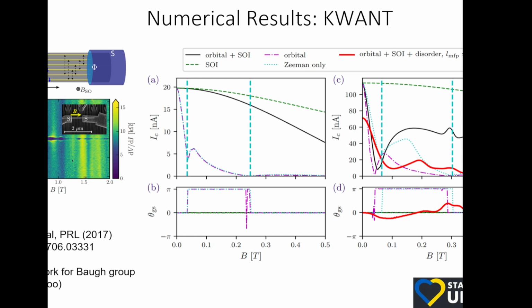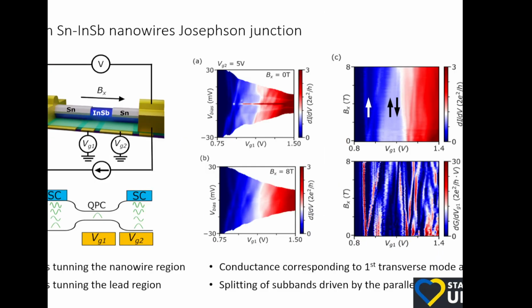Okay, so now I want to talk about the single mode regime. What we are blessed with in these nanowires, indium-antimonide nanowires in particular, is that they are very, very clean. And we did see, in a number of experiments, quantized subband transport in these wires, known as quantum point contact. How many of you are aware of quantum point contact?